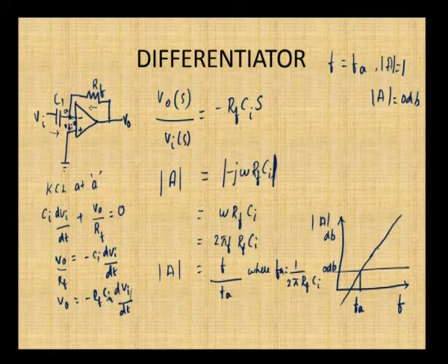And the next problem is, at higher frequency the capacitive reactance of the capacitance C is inversely proportional to the frequency, so if the frequency is high, the capacitive effect is very low, and this system is sensitive to noise. These are the two disadvantages we have seen in the basic differentiator, and so we are going for the practical differentiator. We will see it after the break.